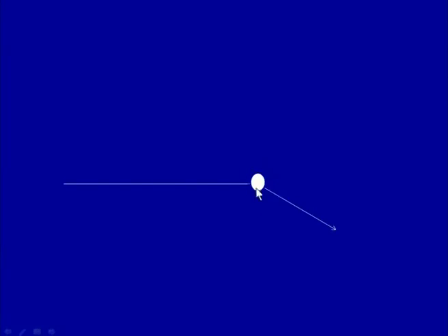weld joint. So, we know that for showing the welding symbols, we first need to draw one horizontal line. This is termed the reference line, and connected to one end of this reference line we draw one arrow line. This arrow line indicates the location or the side where the weld is to be made, and when a round circle is made at the junction of these two lines, this indicates that a weld is to be made all around the periphery of the two members being joined.